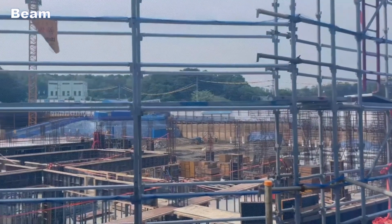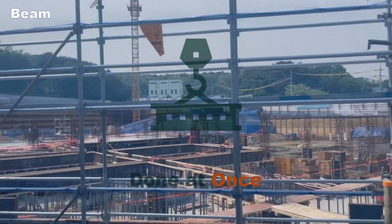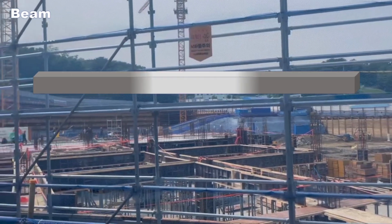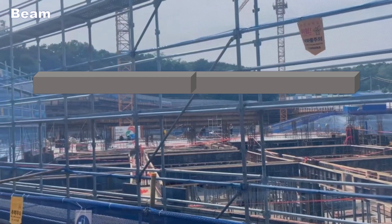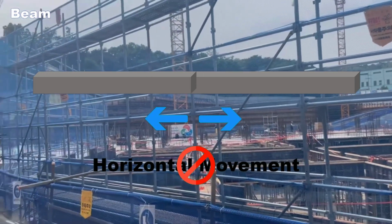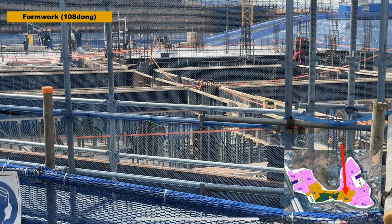Unlike columns, beams are installed all at once, and concrete is poured from both ends toward the center, with the principle that the poured concrete should not move horizontally in the formwork. At our site, we were able to confirm the completion of the beam installation process up to the formwork stage for the basement of Building 108.